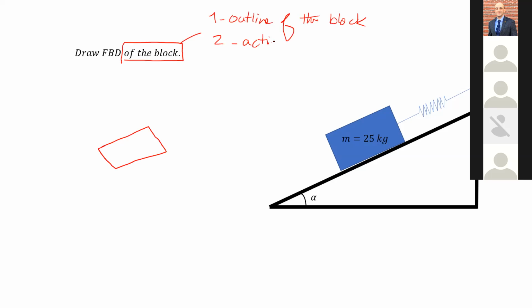Step 2, active forces. What active forces do you see on that block? Or you don't see, but what forces are there at play? Weight. Just the weight. What else? The tension force. So some people might argue that's a reaction, or I would say reactive force, that's keeping it in equilibrium. But some people say since it's a tension, it's an active force. Either way, all of those people are correct. W. If you want, you can put a tension or F spring here.